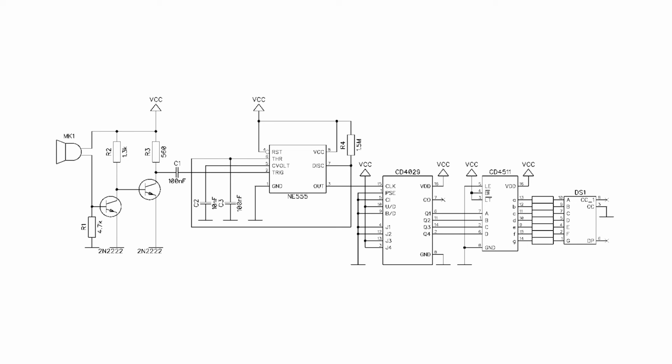The capacitor connected between the amplifier output and the NE555 input decouples the fixed component. It allows only the variable signal to pass. The system on the NE555, already at the first stronger signal, latches at the output a pulse with a duration so selected that at one clap there is one impulse, and that at faster clapping it does not omit any that you want to count. The CD4029 system is an integrated pulse counter.